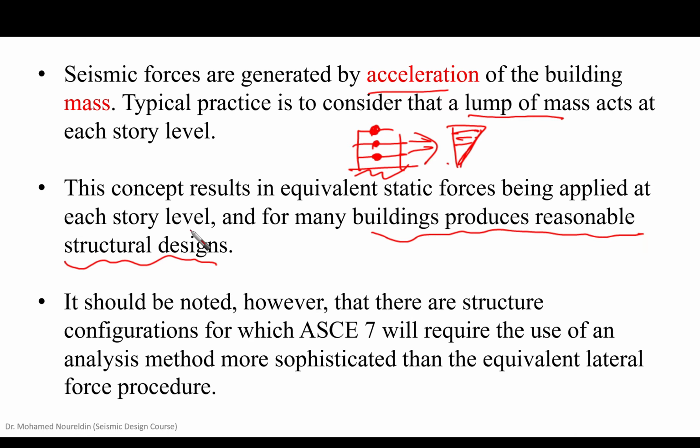This means that there is an engineering judgment here that should take place, that we found that the previous designs of the previous buildings survived earthquakes. This means that our strategy, our approach is okay, it is right. So this is why we said that from the practical point of view, the equivalent static force method is a highly acceptable method.